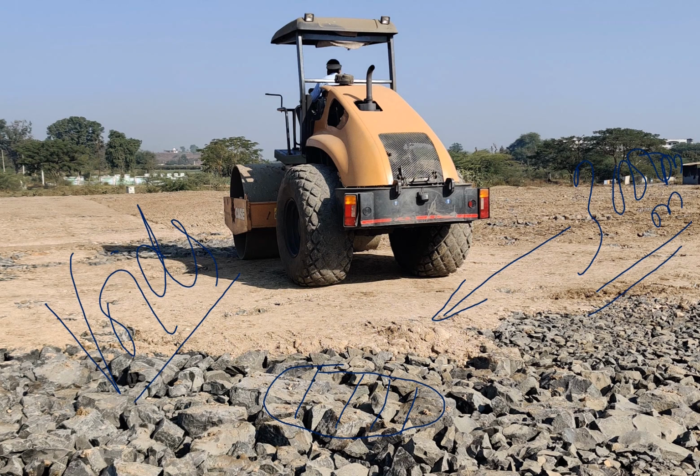So this is showing the typical cross section of each layer, a combination of rock and fine materials, and on top of it again rock fill and then the fine materials to seal it, followed by the confinement on both the sides, and then the top of the soil being treated with 2 layers of embankment, and then the final layer of subgrade to close the rock fill embankment construction.